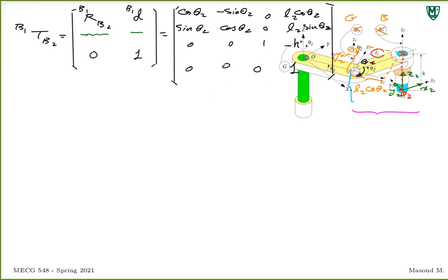If it was rotating this way and your end frame was in the negative direction, your theta 2 is negative. The cosine of a negative angle, as long as you're in the fourth quadrant, is still going to be the same value. Sine is going to be negative. So don't worry about that. The mathematics of this formulation is going to take care of that positive and negative. We always write it with the positive sense, at least in most cases.